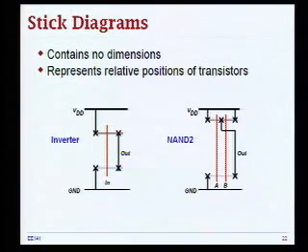You have all these standard cells with various flavors. Now the thing is, for example, if you put a standard cell of your unit size inverter, then you have a problem when your fan out is too large. And to accommodate that case, you typically have a variety of sizing factors for a given function. So for example, you have 1x inverter, 2x inverter, 4x, 8x, 12x, and that's about the number they go up to, like 12x, eventually 16x drive capability. And the same thing you have for all the other cells, NANDs and so on.